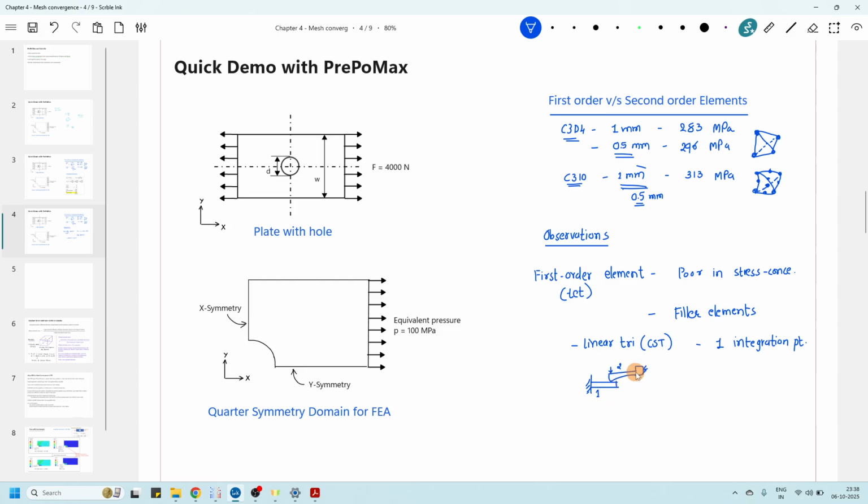Since we might think this area is not of interest, we are meshing this zone with the C3D4 element. Now it may happen that when we apply the force, in reality, components 1 and 2 are supposed to make contact with 10 Newton, but since C3D4 elements are stiffer, they might make contact with 12 or 15 Newton.